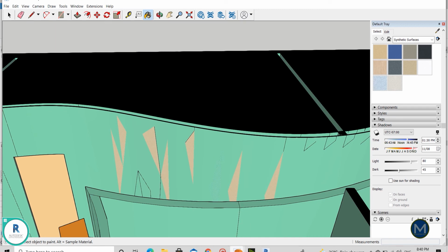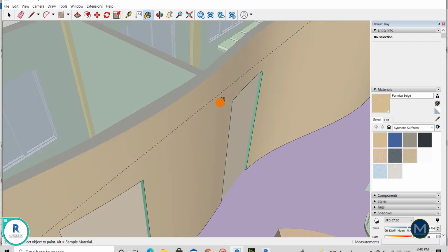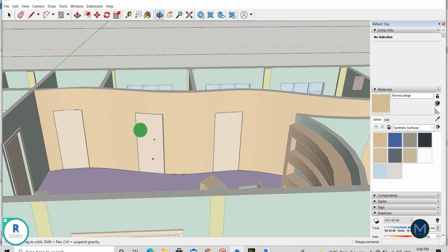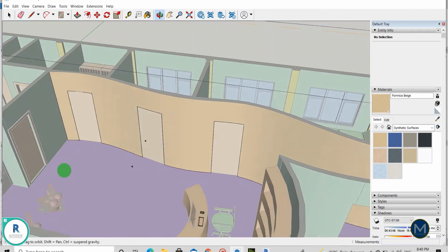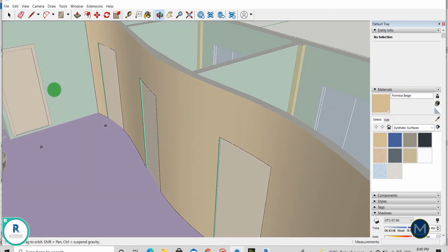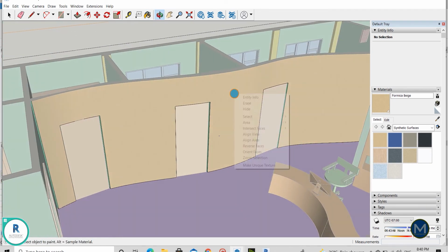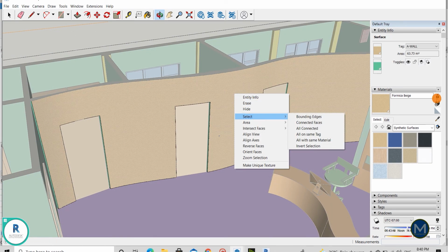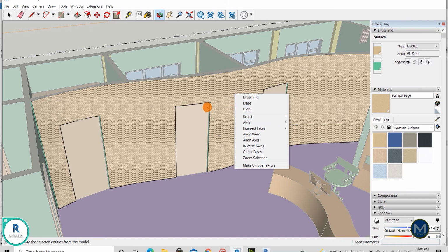So after you adjust the export setting to be the ACIS model, it will become a pure solid and smooth. So you can just pick up your material and paint all your geometry and components in your SketchUp model.